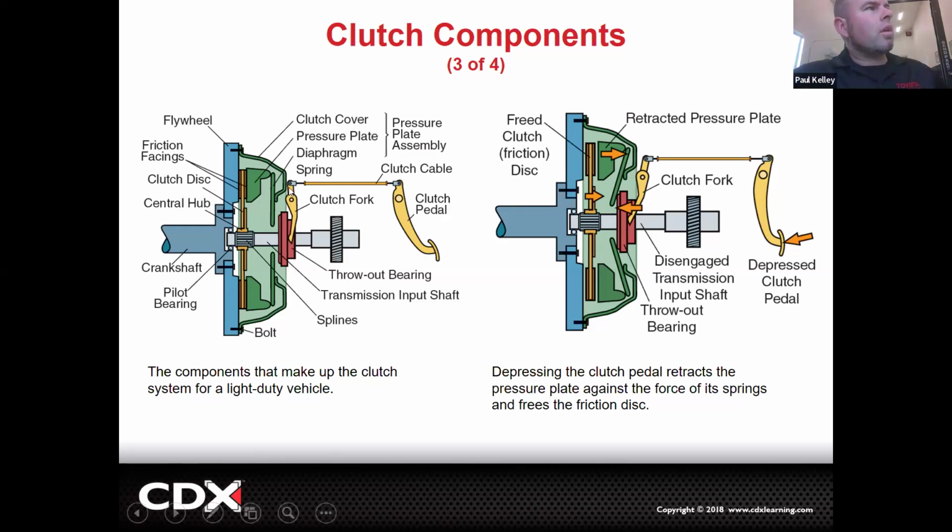So if you look in this one, your clutch is engaged, which means the disc is spinning with the flywheel, which means the input shaft is spinning with the disc because they're splined together. That means your input shaft is spinning. You know, we have a bearing right here. There's a bearing just barely inside the transmission, a lot of times called the input shaft bearing. That bearing would be spinning with the clutch engaged. So let's say you hear a noise, you can hear that, right? But you vary your pressure on the pedal just a little and it makes no change.